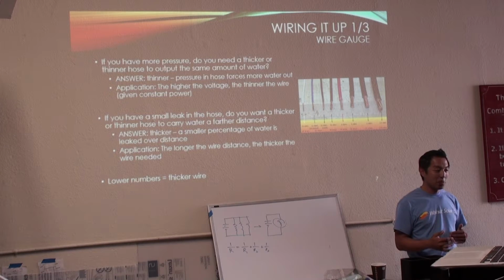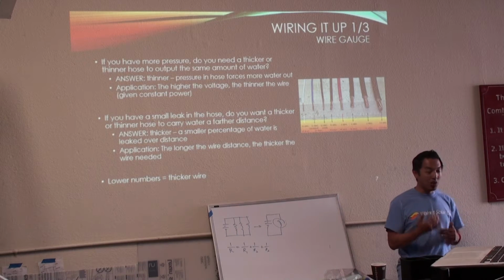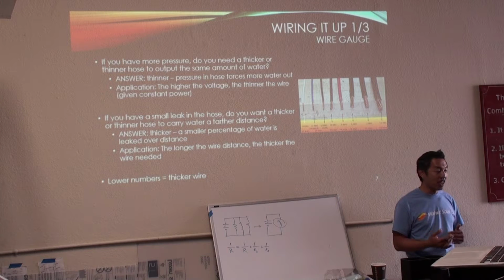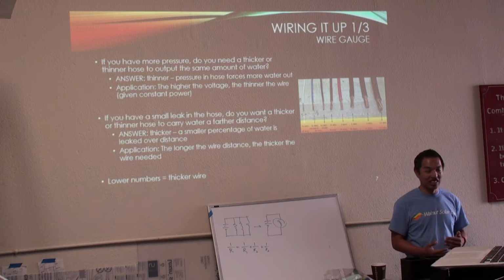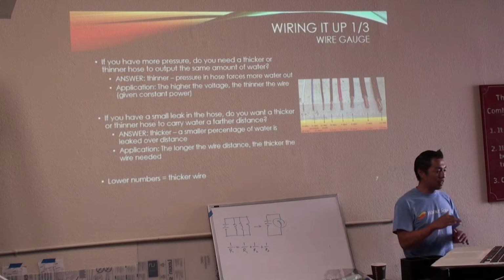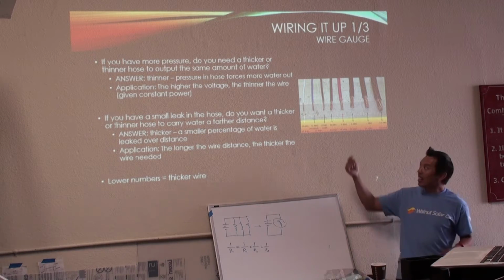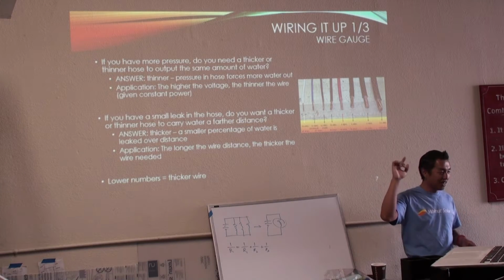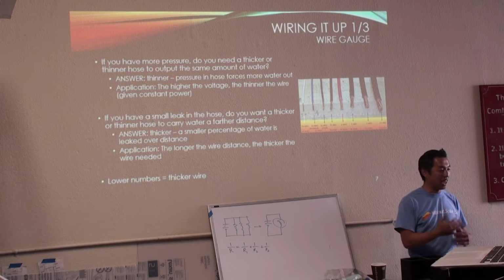But if I discharge it at 20 amps, I'm not going to get half an hour. It's not linear, so we can find out via the graph how much capacity we actually have.